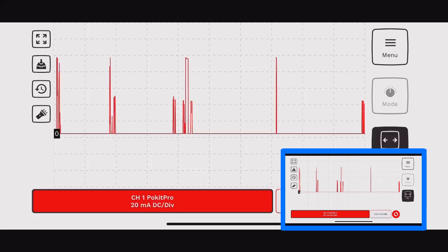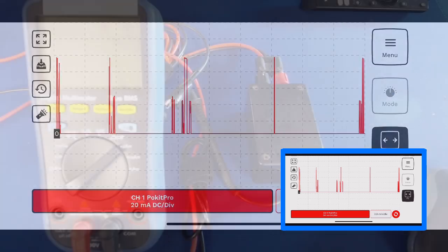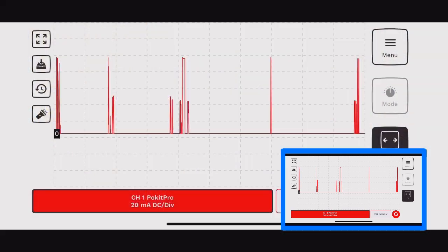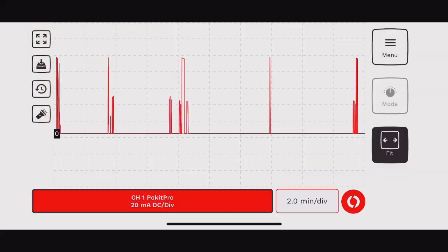It's showing the spikes on your graph, which is a whole lot better than trying to look at that meter and go, oh, I see it floating, because guys, it's going to float. And you're not necessarily going to notice as much that it's staying within the bandwidth by using that meter than you are using the logging meter that has a graphic function.